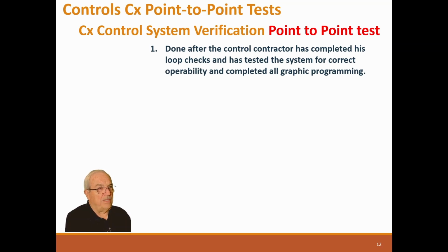Now, they don't have to be 100% done. They have to be done so that we can see every point and we can override every point that's overridable. That's really important. Maybe they don't have a fancy floor plan graphic done. We don't care, as long as somewhere we can see the room temperature, room humidity, and everything else, and we can deal with that. So they actually need to be done. This would actually make a control contractor a whole bunch of money if you do this regularly.